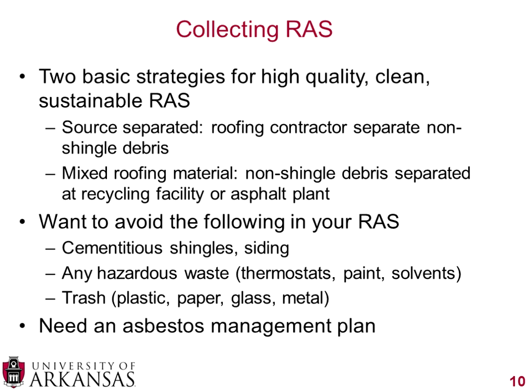You could potentially save that, and that's assuming 100% blending, and that you're getting the asphalt cement properties that you want out of that 100% blended material. So potentially $40 to $50 a ton, but I think that's a very high-end value, and that doesn't include the cost of obtaining the material and then the cost of processing it, making sure that everything's ready to go, grinding it, and then, of course, any sort of plant improvements.